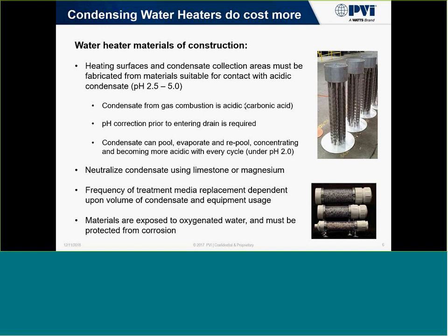And that's also why we need a condensate neutralization tank, which is shown in the bottom right-hand corner. So what that does is it basically takes that condensate and neutralizes it so it doesn't attack our drain system. Like if we have, for instance, cast iron drains, they wouldn't last too long if we were throwing a pH level of 2.5 down the system.